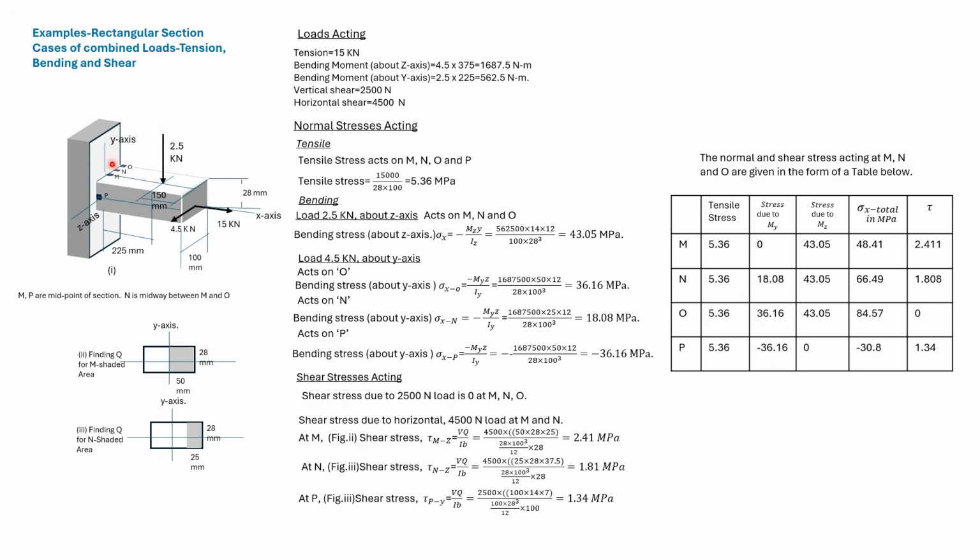This force causes vertical shear and bending moment about the z-axis. So this is the vertical shear and the bending moment about the z-axis. We find the normal stresses and the shear stresses separately. So we first find the stresses due to the tensile load.